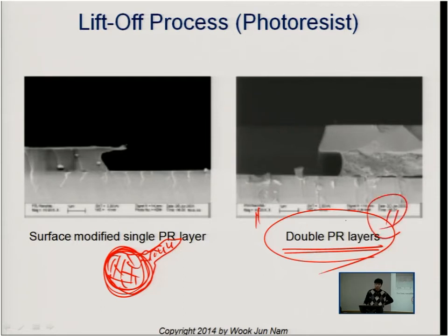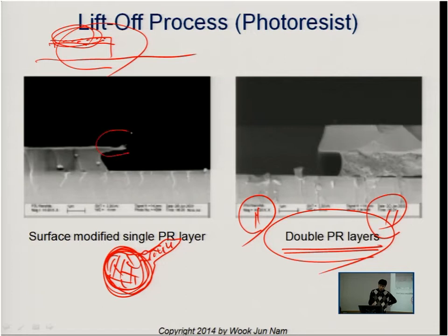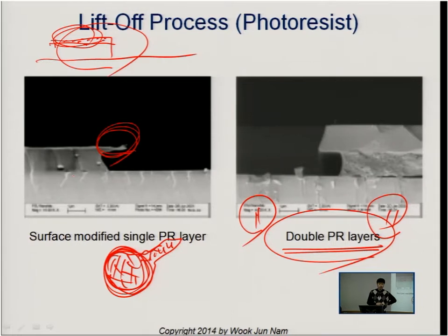Before this kind of resist was developed, what people used was just a single resist. So spin coat a single photoresist and then soak that imaging resist under a solvent like chlorobenzene or toluene. That soaking process modifies the surface of the photoresist. The modified surface of the imaging resist is much harder than its usual characteristics. So after exposure and then development, the dissolution rate of the modified area is much slower. Using those different characteristics of the single material, people can make this kind of latch structure, but the modification of the surface is not that reproducible.